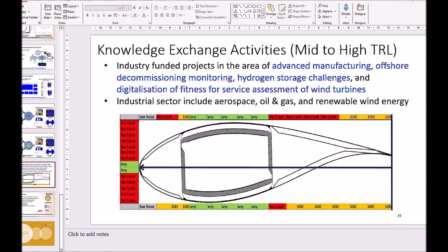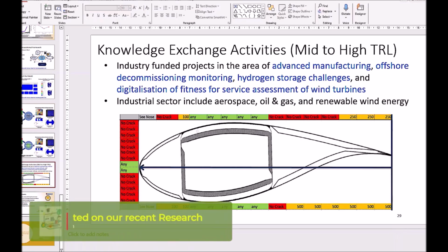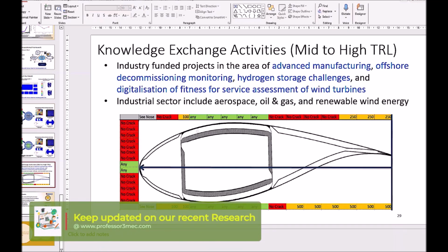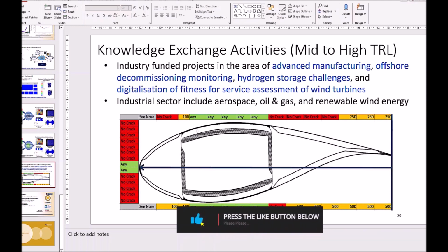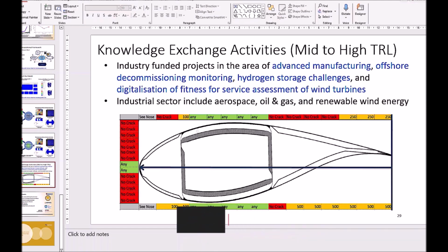So last question. I am dealing with the phase transformation model. When we talk about phase transformation, there are two ways to define it. One is the thermal phase transformation at high temperatures, those phase diagrams we have. And the other one is the mechanical transformation. So we currently work with the mechanical transformation, which is generally termed as transformation induced plasticity. For example, I gave you one of the examples at the end, for the metastable beta titanium alloy.